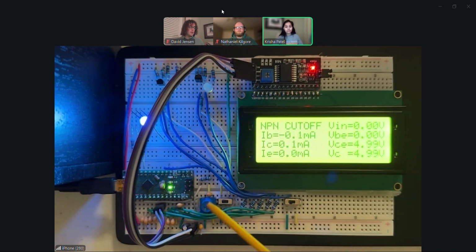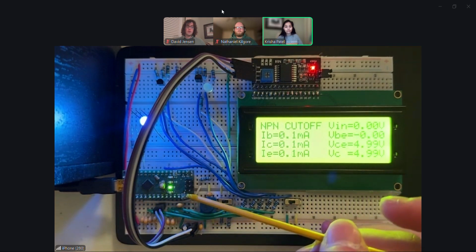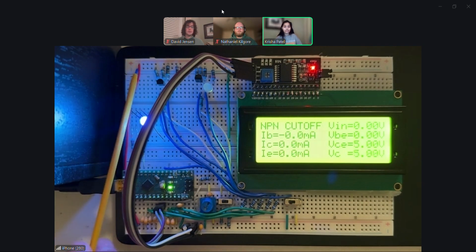So now I'm going to go through the flow of the circuit, tracing it through. Along this row of the Arduino, we have all of our analog inputs and outputs, as well as our 5-volt and our ground pins. This other side has all of our digital inputs and outputs. So starting here, we pick up 5 volts and ground, and we supply that to our power rail. It runs all the way along here. We also jump that up to the top side so we can pick up power and ground from any location.